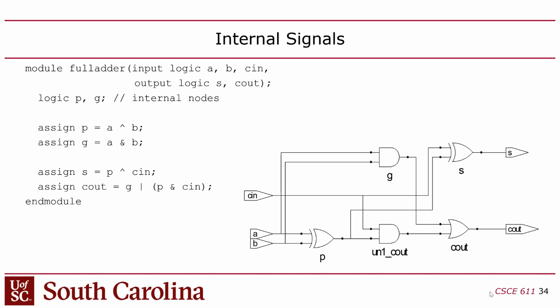You guys with me? So when you write Verilog with the intention to synthesize it to hardware, you have to be a little bit more careful about only putting in there synthesizable Verilog. Whereas if you're writing a test bench that's just for simulation, you could put other things. So this logic data type is part of that. You want to stick to logic if you're using synthesizable code.